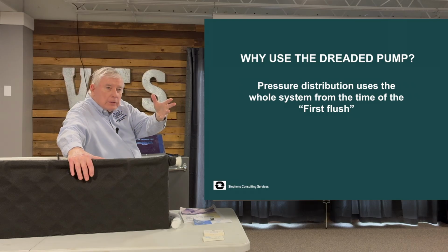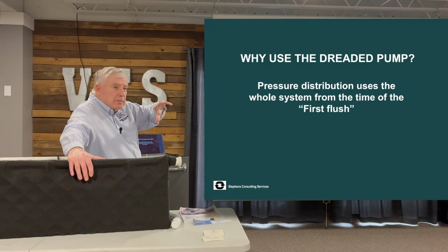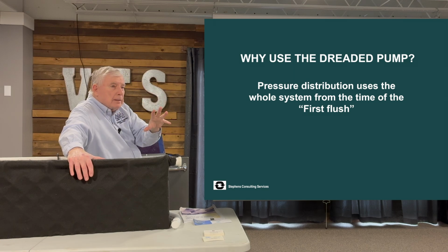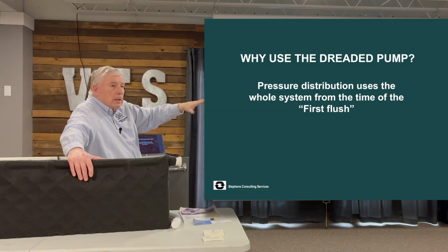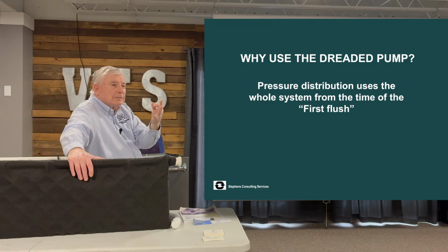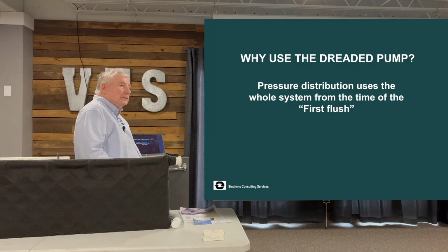Doesn't mean what counties require systems to be designed for. They require 6 people per household and all that. So they want to design it for 450. But regardless of that, it's 150 gallons is what you would expect out of an average household in the state. So 150 gallons at a 50-gallon a minute pump runs 3 minutes a day. So we'll talk a little bit about that after lunch.